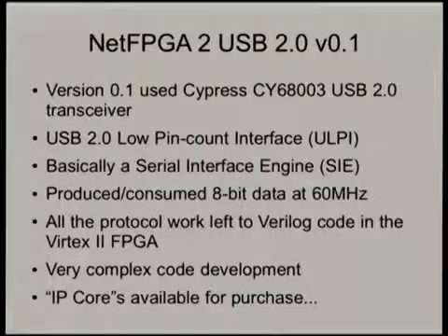It basically relies on implementing most of the USB protocol stack in FPGA code. There are some implementations available, especially on the Open Cores website, the open FPGA type work that people have been doing. But it was still going to be a huge amount of work implementing an interface using those serial interface engines and then putting all of the USB code into the FPGA. So we could have bought some IP cores for using with that, but instead I decided at some point to go back and try a new design.